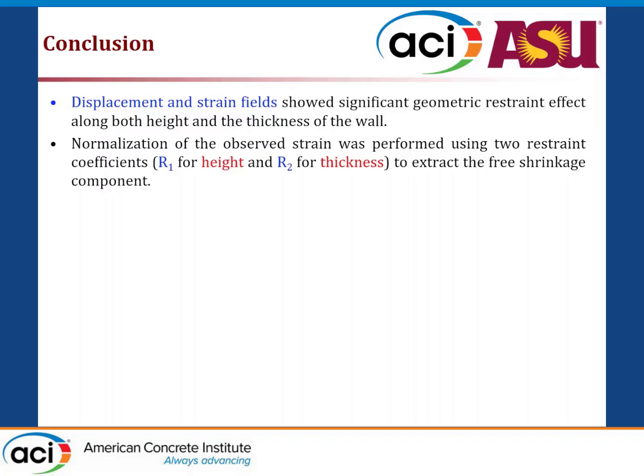And we can have a rationale for what happens if you print a double wide filament wall, or a 4 filament wall side by side. Shrinkage will obviously decrease for your total, but because there's higher restraint, you could end up having cracks, because the material actually wants to shrink whatever it wants to shrink. You are restraining the shrinkage; you are not removing the shrinkage at this point. So it might crack. There might be problems because of those reasons.